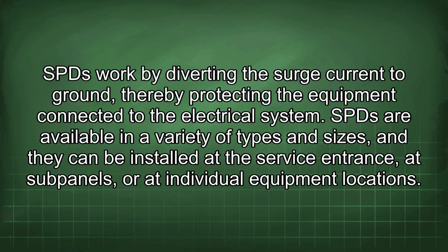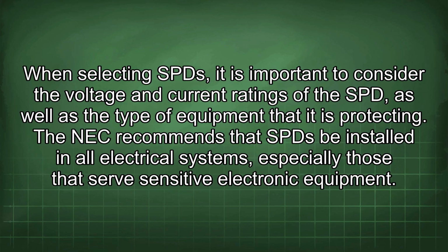SPDs are available in a variety of types and sizes, and they can be installed at the service entrance, at subpanels, or at individual equipment locations. When selecting SPDs, it is important to consider the voltage and current ratings of the SPD, as well as the type of equipment that it is protecting. The NEC recommends that SPDs be installed in all electrical systems, especially those that serve sensitive electronic equipment.